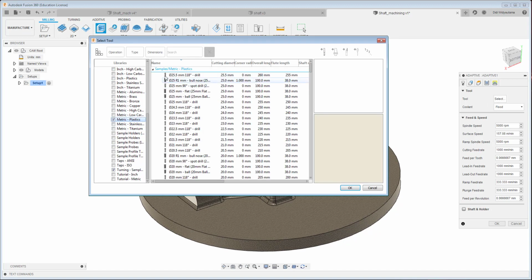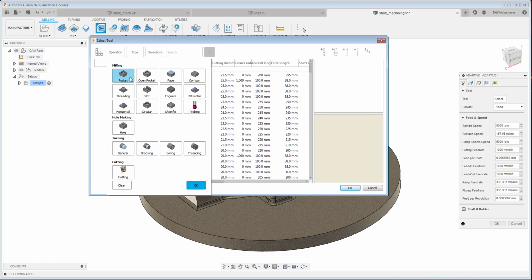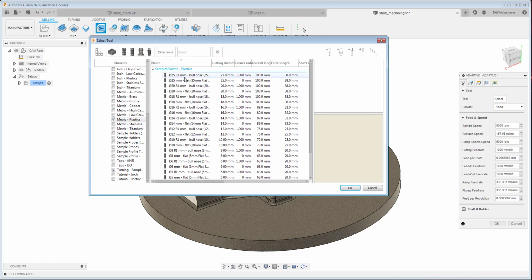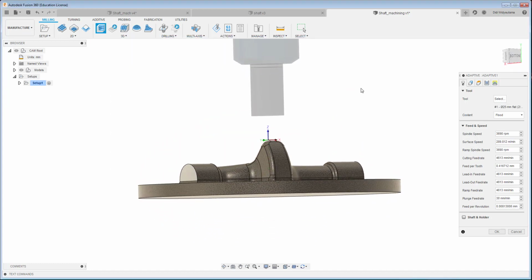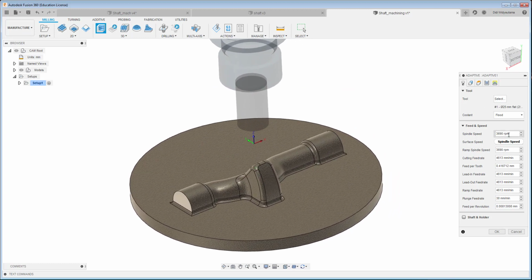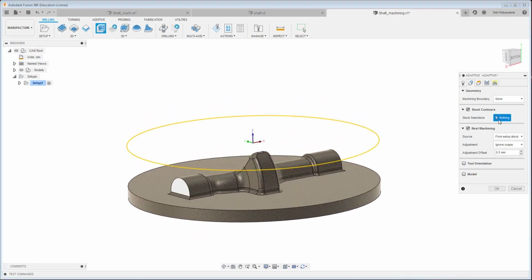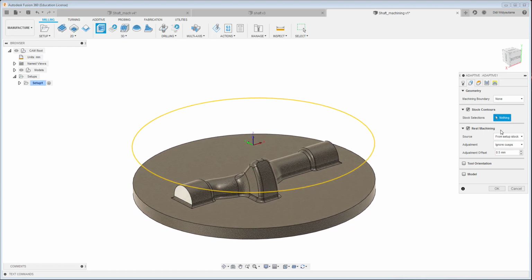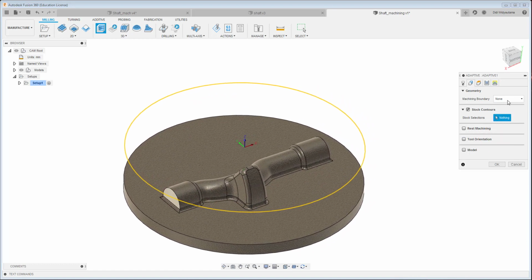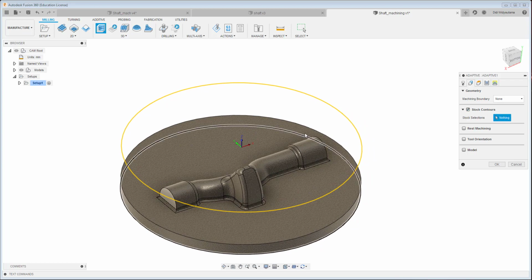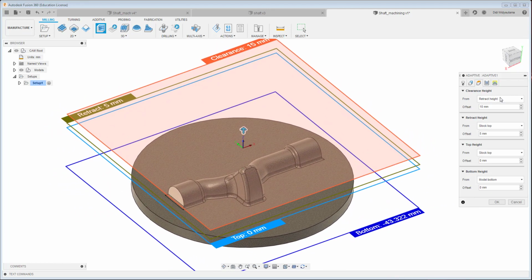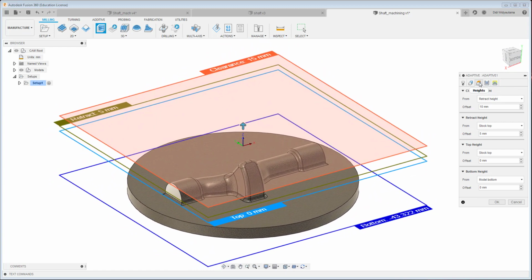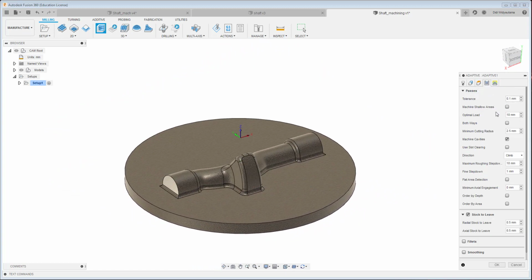This I will make from plastic, so I'm going to use the end mill flat. Okay, end mill flat, for the first roughing, and then the geometry. Okay, this is not the best machining, so the stock contour, okay, that one, and also the height and also the passes.